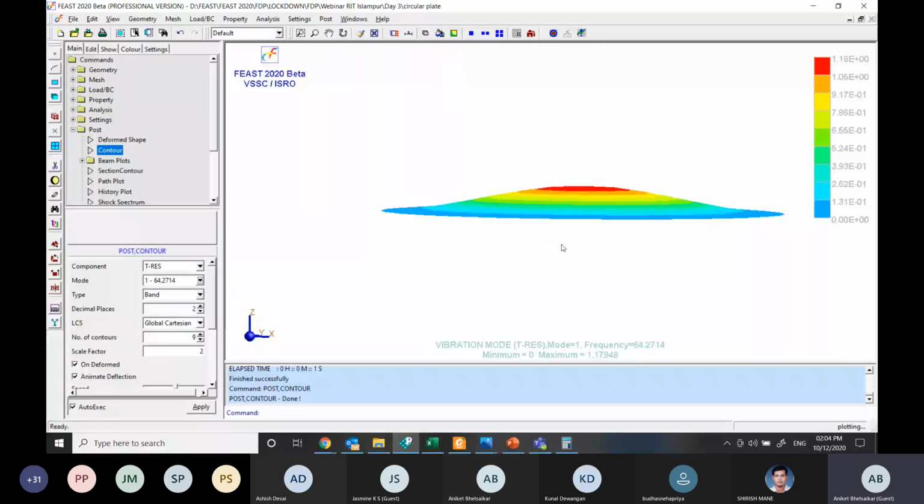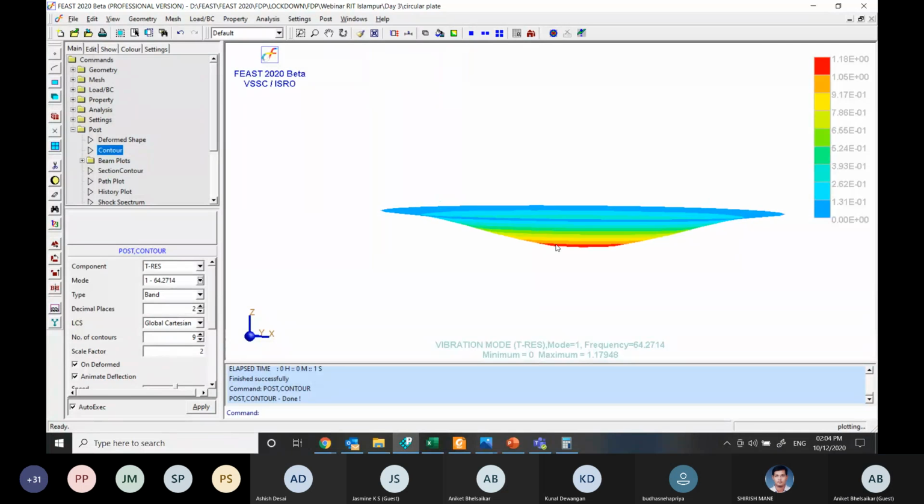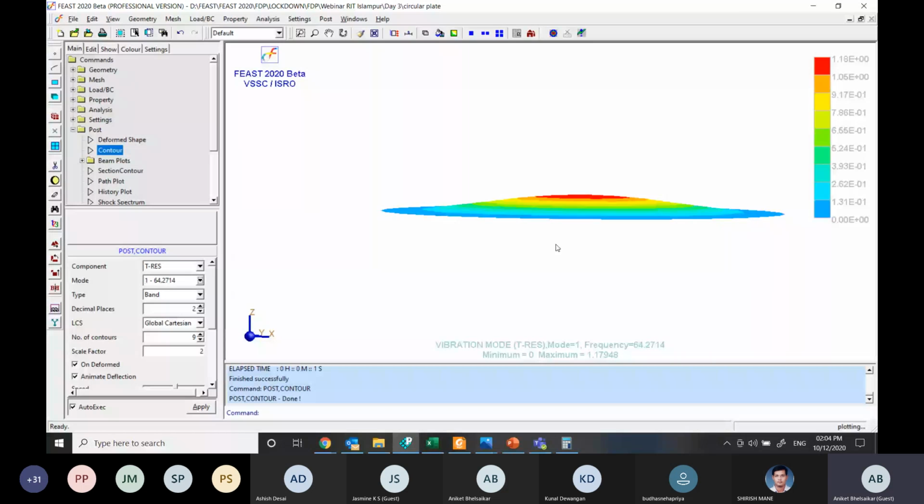Because of these vibrations, because of the movement to top and bottom, it will have a serious impact on the operation of the robotic manipulator, which can cause bolts to loosen, or the accuracy of the robot will be badly affected, because even the gripper will start vibrating.